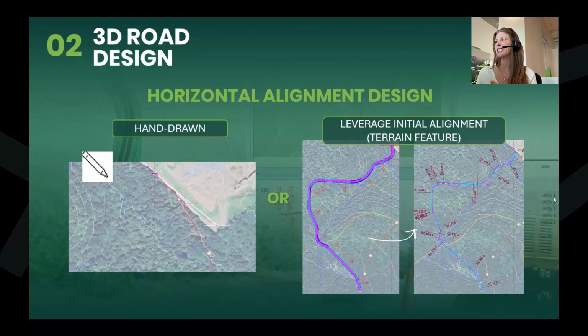You could come in with GPS points or Path Explorer, and we can leverage that. Use a tool called Polyline to alignment on it, turn it into horizontal alignment, and start to really work on the actual details of our design. Sort of two different methodologies, and they can be intermixed. You could hand and manually adjust that initial alignment feature as well.